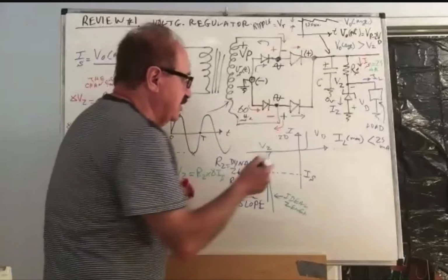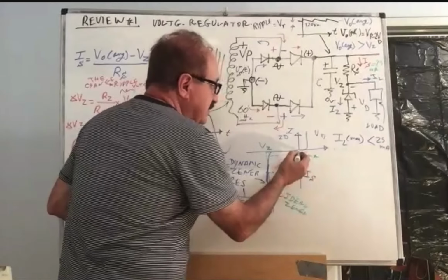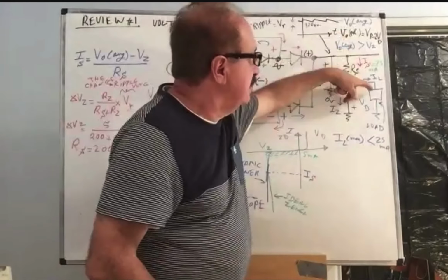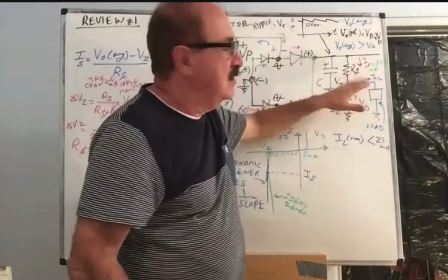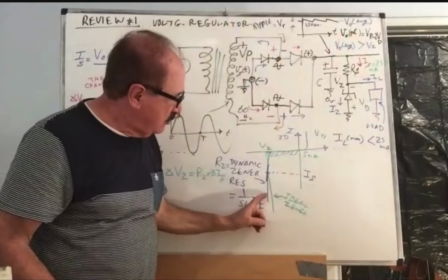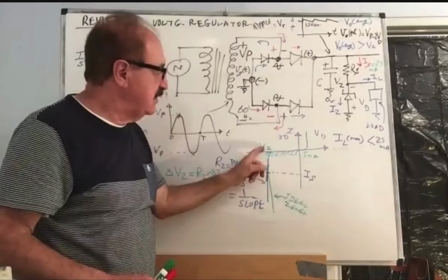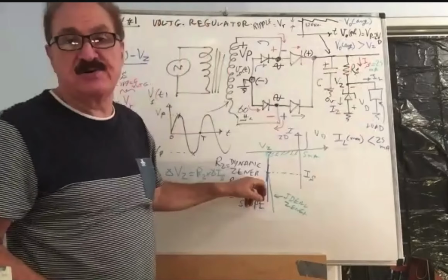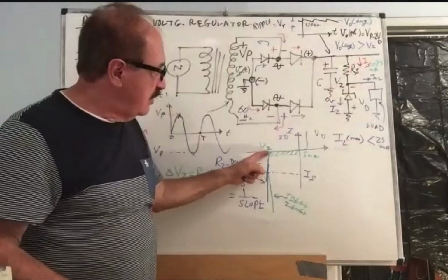Usually this threshold is about 5 milliampere. They say, look, if you're going to steal from the source current with that load, allow some current to flow in the Zener. In other words, allow yourself to come up all the way to here, to the 5 milliamp. Don't deplete the current that is intended for the Zener, to keep it deep into the Zener region. Don't bring it to zero. Because if you did that, you will get into the deregulated portion of the Zener.